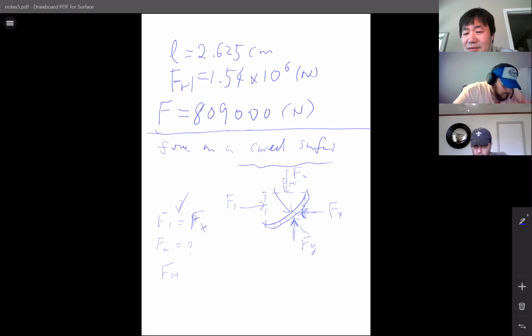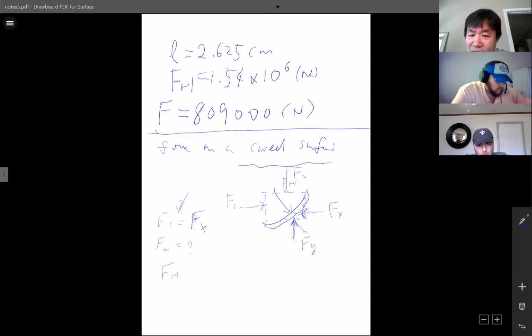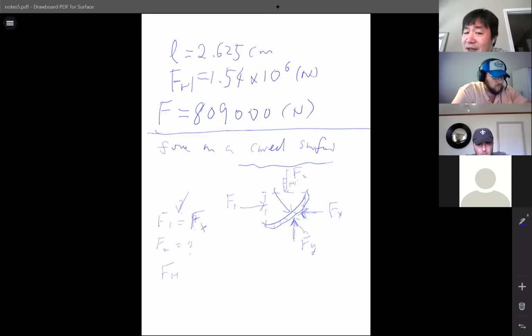Now, this is the knowledge we covered in the previous couple of classes, for a plane surface, depending on the shape. Now it's a plane surface, nothing new, nothing curved. F1 is just the force on this vertical plane. So find the centroid of that surface, measure the distance between the centroid and the top water surface. Gamma times this h is your overall force on that vertical plane surface. It's a virtual surface, but it's plane. So you should be able to calculate F1.